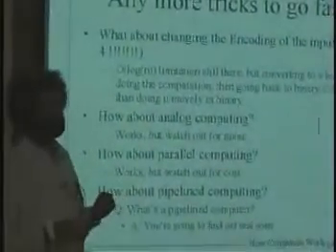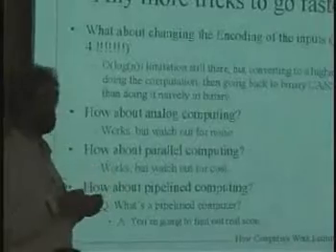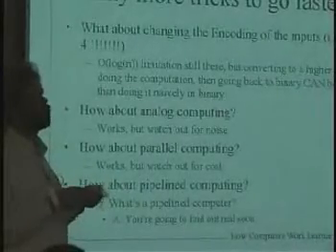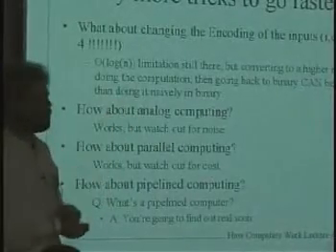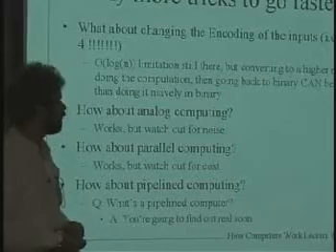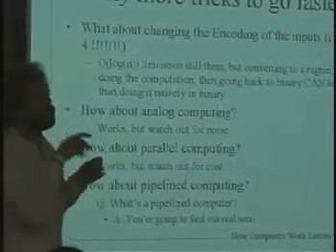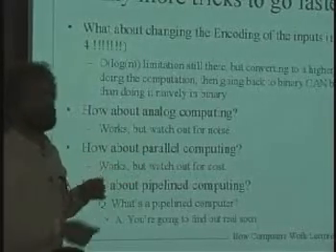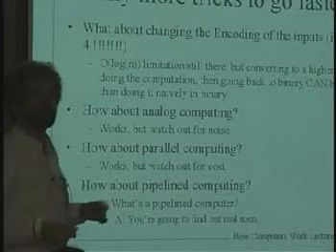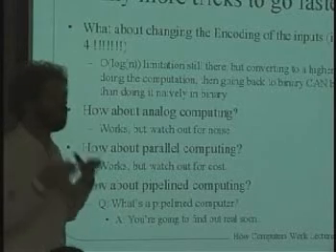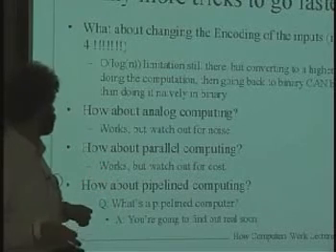Parallel computing, again, is a way of making things faster, and we began to get a little bit of a hint as to how to do that. Either the crazy example of a lookup table with 2 to the 70 entries in it, or looking ahead to the G and P bits more and more and more. But again, you have to watch out for cost, because the more you do this look ahead, the more hardware there is in order to do it.